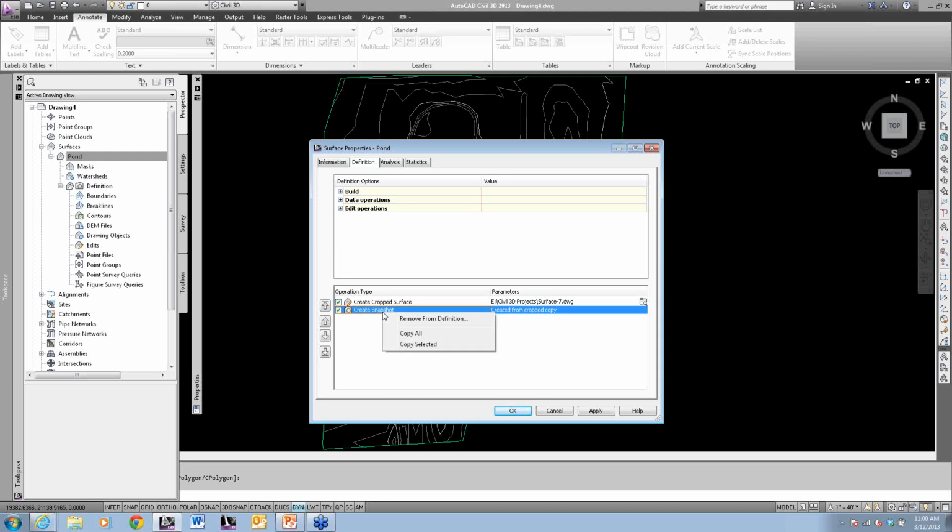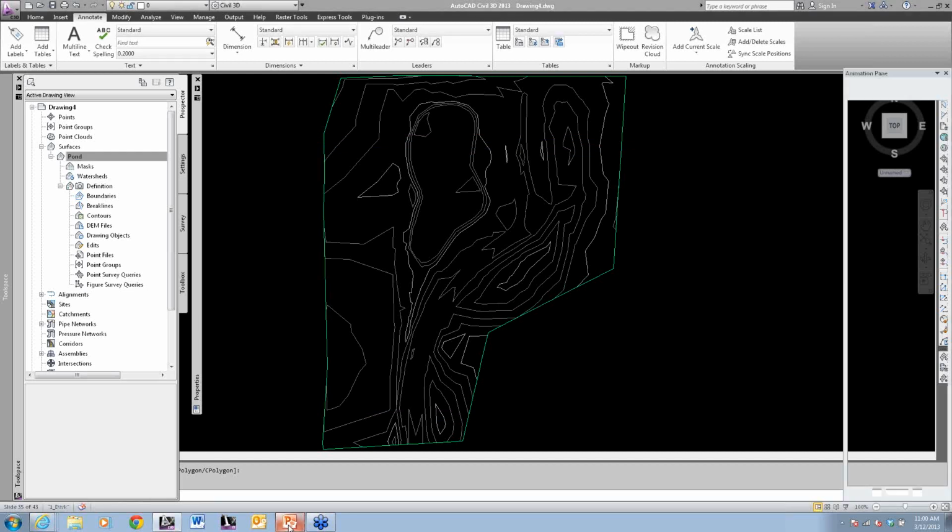Basically what a snapshot is, it says, okay, this is the way the surface is now. The next time you go build the surface, start here and ignore everything that was before it, because this is the way it was, and you don't have to go rebuild all that information. For example, if you bring a LandXML file into Civil 3D, you can create a snapshot of it and then get rid of the XML file off your system. If you don't have a snapshot, you need to keep the XML file. So that's a great thing. So there's a nice tip there for you.